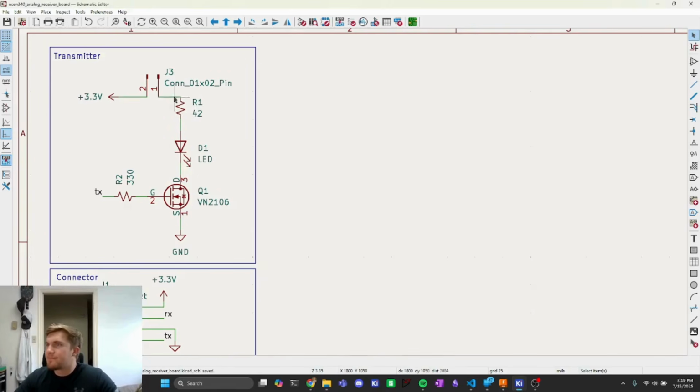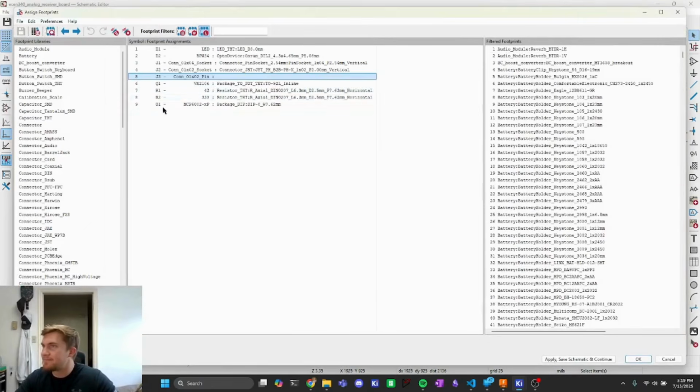Now we're going to put a little hat that's just going to bridge these two pins together. It's a little part you can buy in the shop. It sits on top of these two pins and connects them whenever your circuit's not being tested. But whenever you want to test it, you just pop the little hat off and hook up a multimeter probe to each side, and you're testing current. That's super happy.